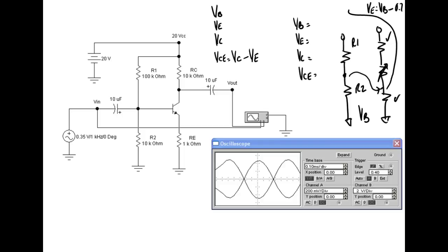It's very common when people do that to think zero is a zero. A lot of people just say, what's the color code for 100 ohm? And they'll say brown, black, black, because they see zero as the zero. But remember that last number is how many zeros you add, right? So if I want 10 and then a zero, it's brown, black, brown, which would be 100 ohms, right? People get that every time. I could put that on the test. What would be the color code for a 100 ohm resistor? And somebody in this class is going to put brown, black, black.